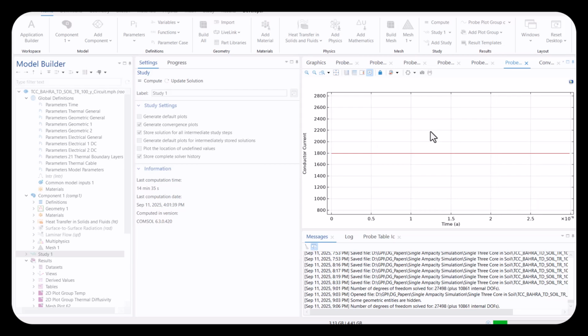Let me tell you, when would a transient ampacity calculation be necessary? When is it important? Some industrial manufacturing processes require a large current being drawn and applied for a short duration. It could be a few minutes, it could be an hour, or whatever the case. So industrial facilities, motor applications.